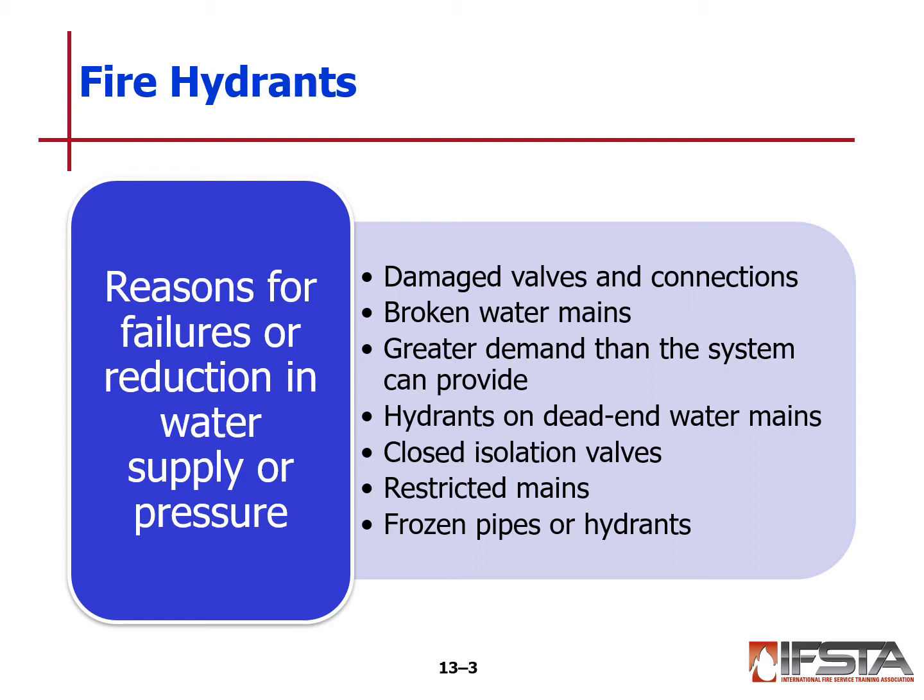In these older water mains and older systems, and Lexington and Frankfurt deal with this quite a bit in some areas, you get calcifications and debris and sediment inside these water mains, and that can cause restriction. And then frozen pipes or frozen hydrants. If you get a hydrant that doesn't drain down properly in a dry hydrant situation, as we have here in Kentucky, if that does not drain down, then we could have a frozen barrel, and that can do damage to the stem, damage to the valve, damage to the bonnet, so on and so forth.